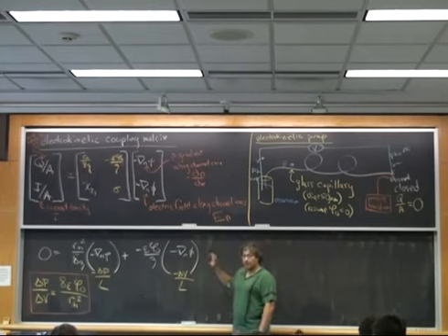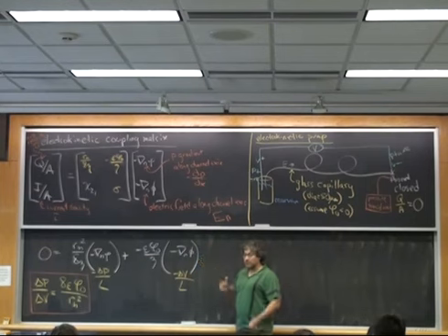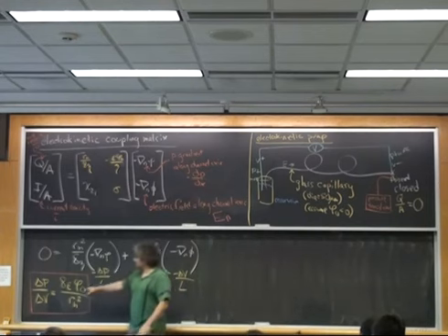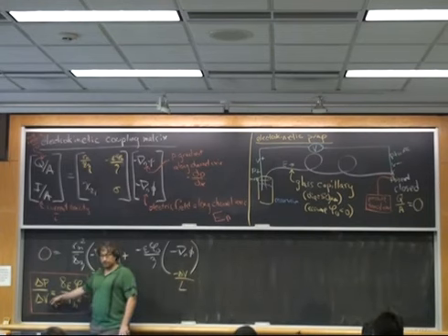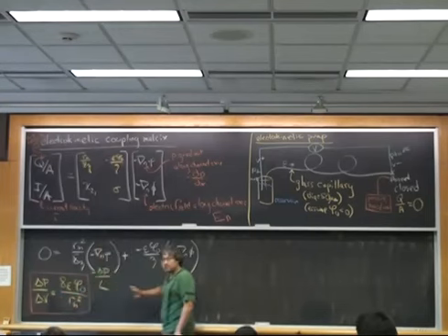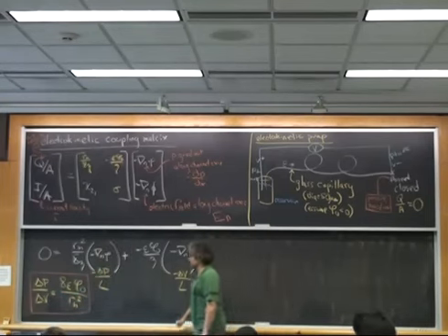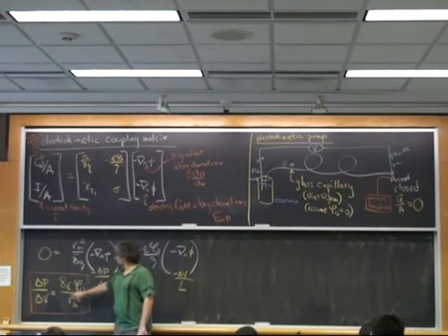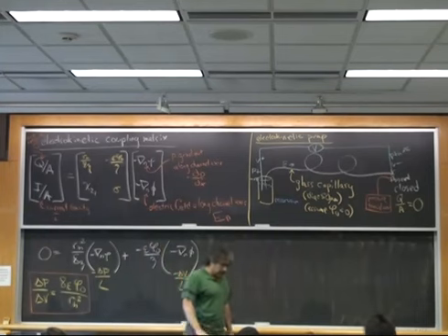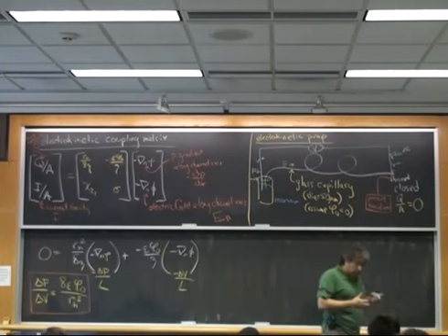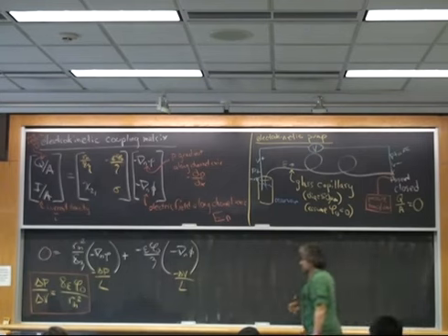So if I made an electrokinetic pump with honey, it would take really, really long to fill up the mechanical compliance of the system as compared to the one with water. But my final delta P over delta V is always going to be the same, right? So there's nothing here that has to do with velocities. Viscosity is not here.